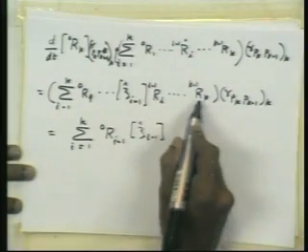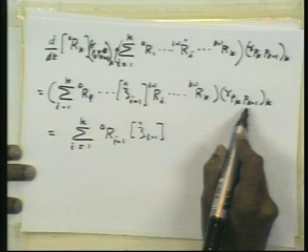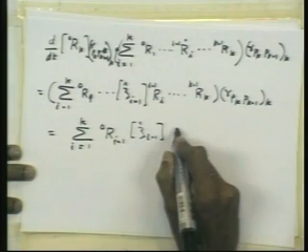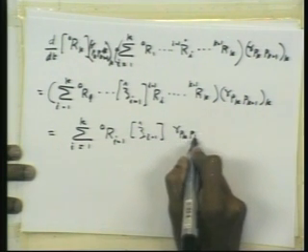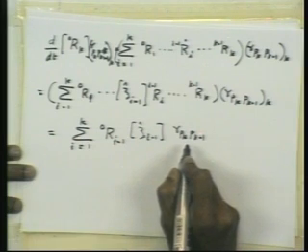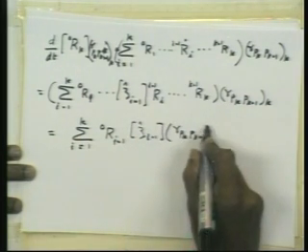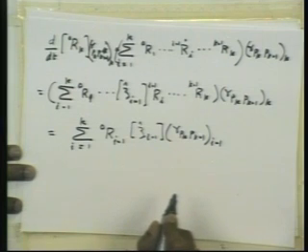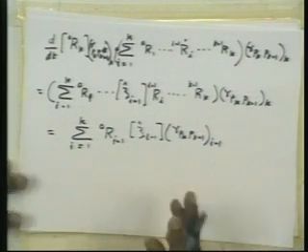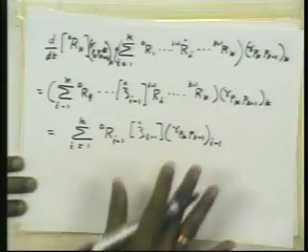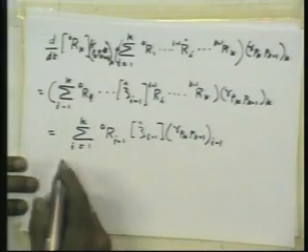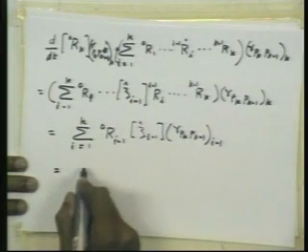Now the rest of the matrices here, and then this multiplied with this, turns out to be R pk with respect to pk minus 1, that segment, in the I minus 1th reference frame. Fine. Now I shift back to the cross product because it's easy to do the remaining algebra there.